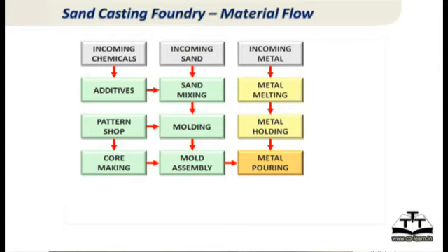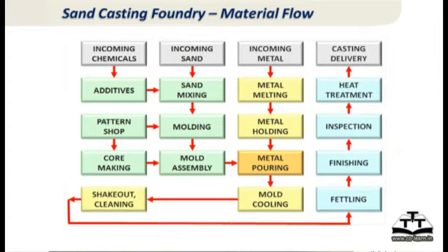The event which everyone waits for is when the metal is poured into the molds. Then the molds are left to cool. The casting has to solidify and then it is left for some time to cool, depending on the size. If it's a large casting, it can take hours. A huge casting can take even days to cool. And then after it cools, you shake out the casting from the mold, essentially break the sand mold, and then remove the casting from the mold.